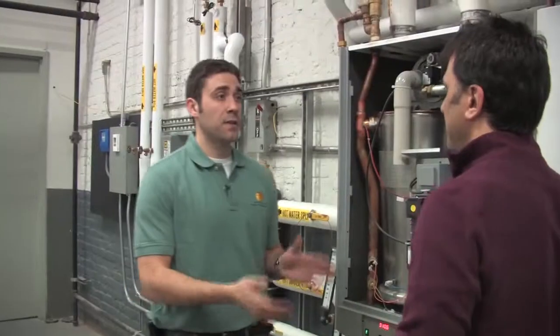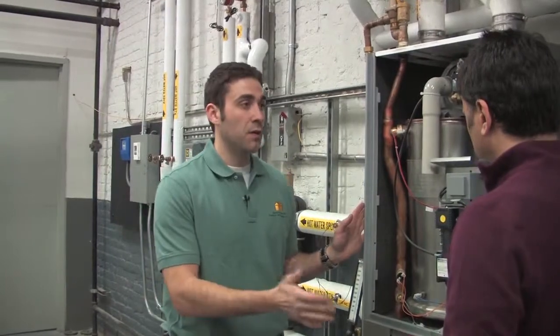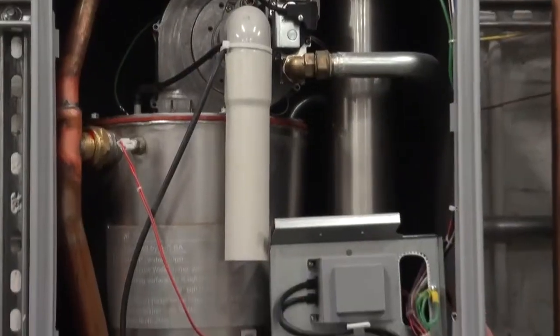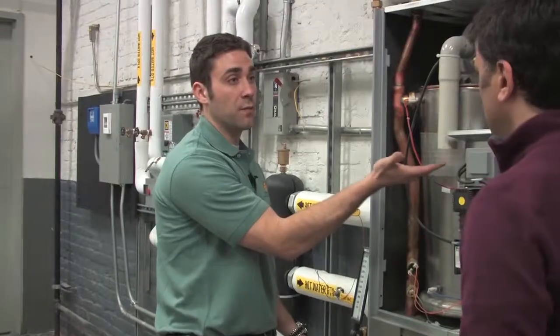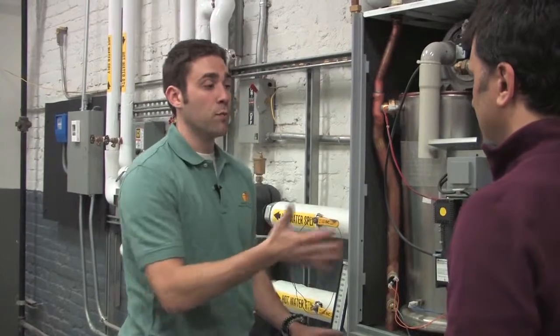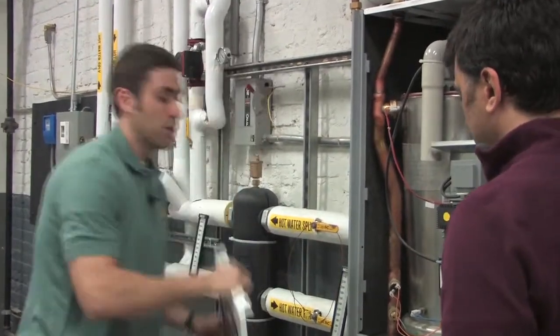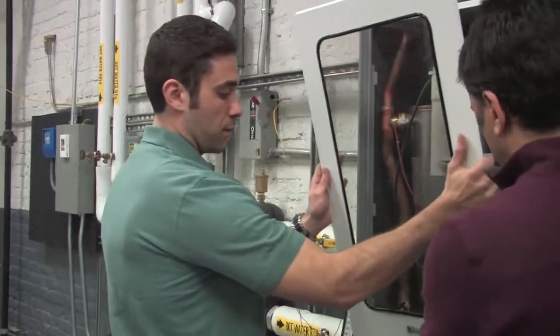We just fired up the condensing boiler, and it's going through a cycle, and it's coming up to steady state efficiency. So we're able to do our combustion efficiency test of it now. So what I'm going to do first, being that the air is being pulled in from combustion right through here, we're pulling in room air, so we're going to seal it up. So I'm going to grab the cover, put that back on.